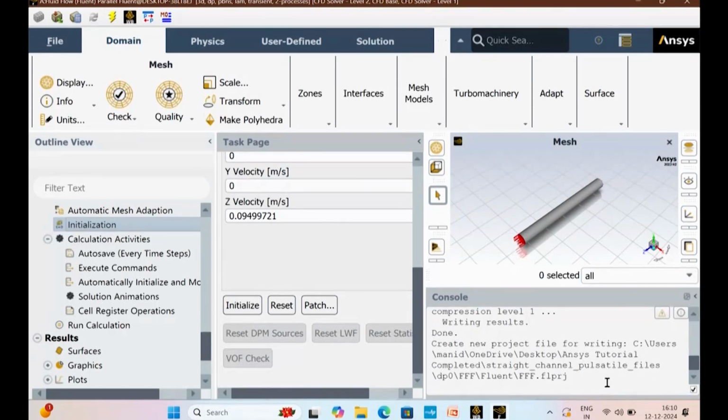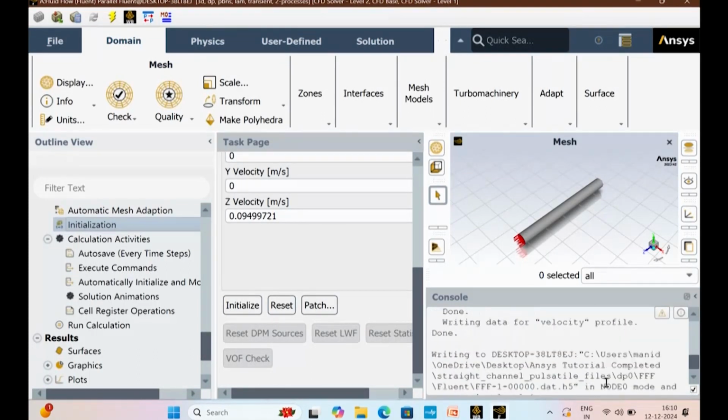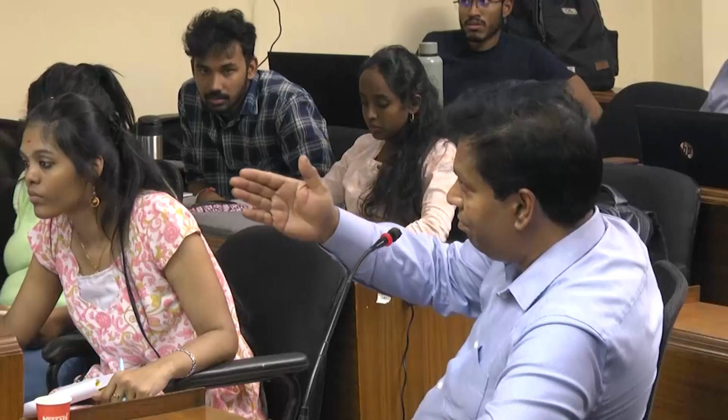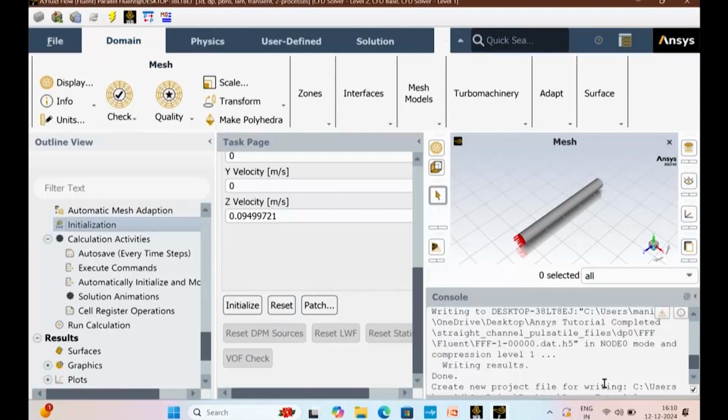No, we are not giving the parabolic. We are giving the average velocities every time. Yes, but after simulation, by default it develops after a little distance. But in the inlet region, no, it is not parabolic. It is not parabolic because it is not possible to give parabolic. Parabola every time is very tough. So that's why he is averaging and putting it there.